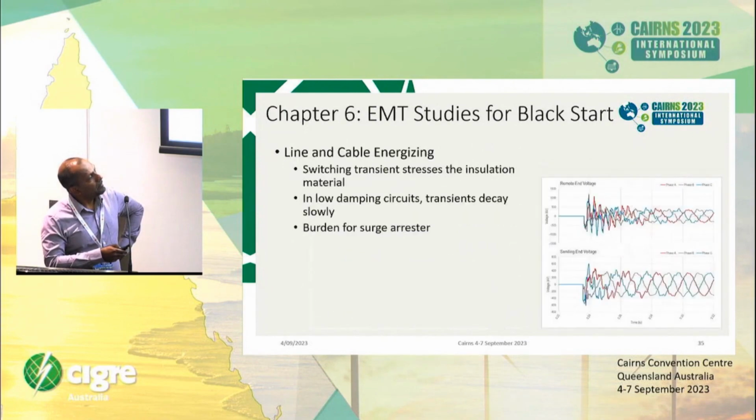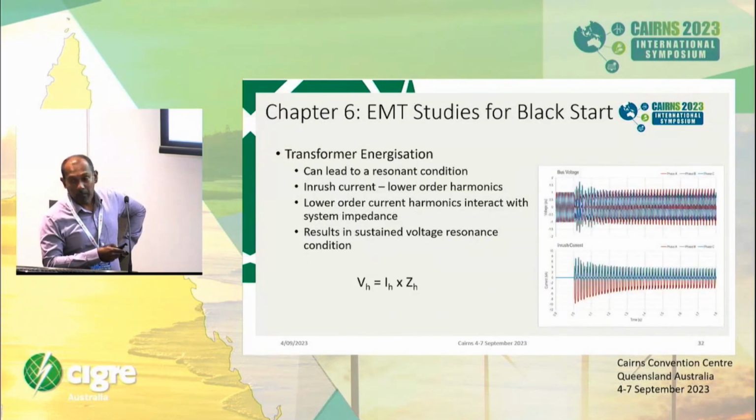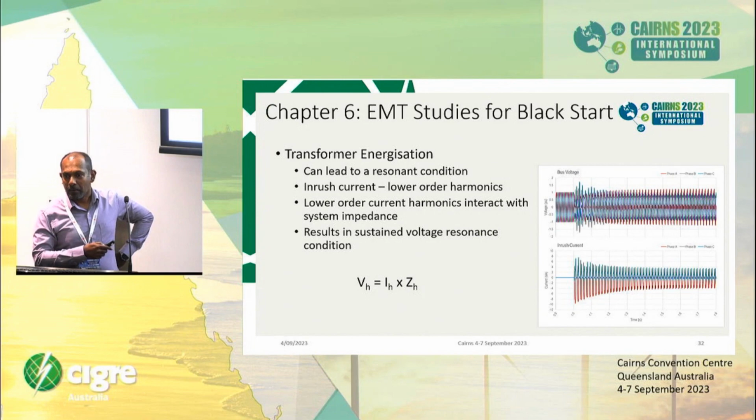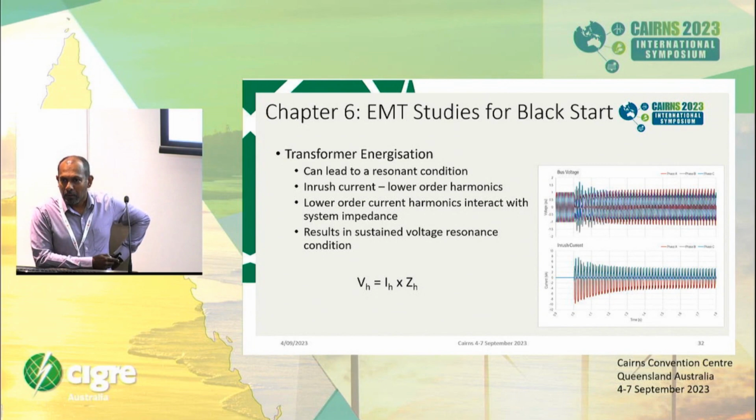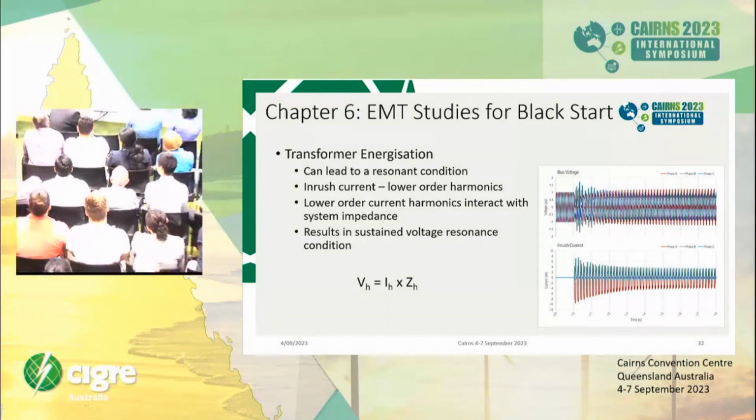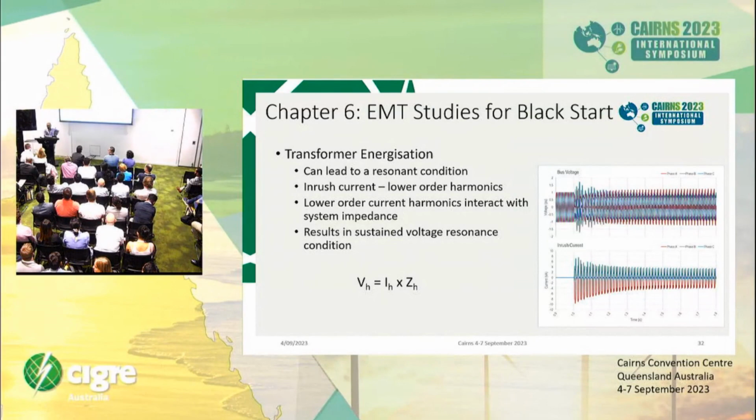I don't want to be an alarmist, but if you stop on the transformer energization, and you've got a lot of inverters which have their own built-in voltage protective software, I'm concerned about voltage spikes caused by L di/dt type issues into transformers.